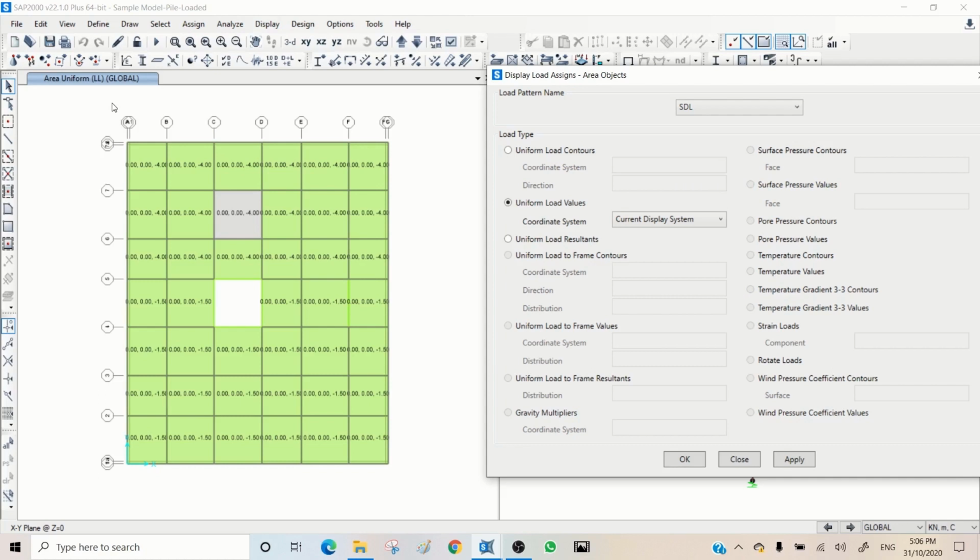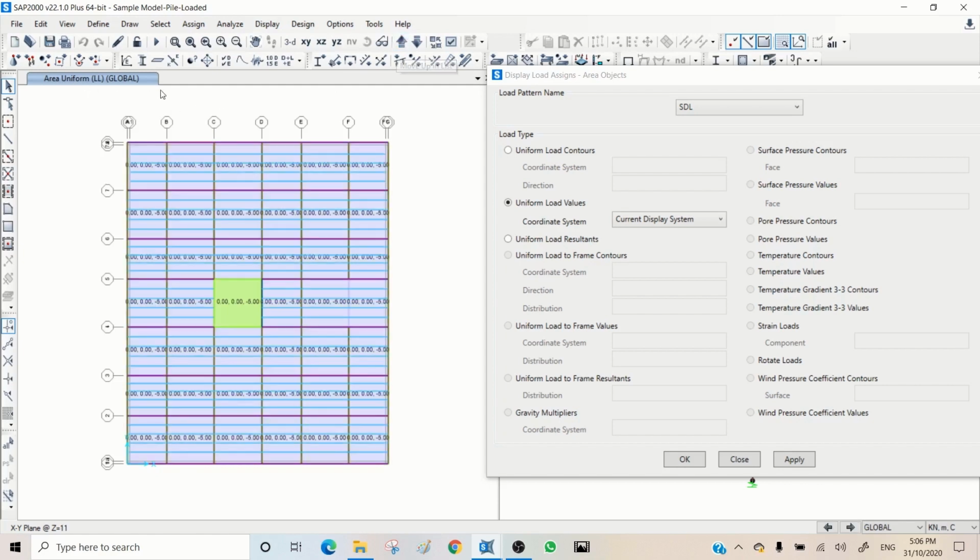So you can see here live load is 4 kPa for this level. If I move on to the other levels, I consider this area as a common area and some, for example, conference rooms or anything that we have more live load. Then our upper levels we have just 1.5 kPa typical live load for residential buildings. And when I'm moving on, you can see for this level, which is upper level, I put, for example, 5 kPa. Just assume, for example, it's a gym or again some area for gathering or conferences. Just some assumptions.